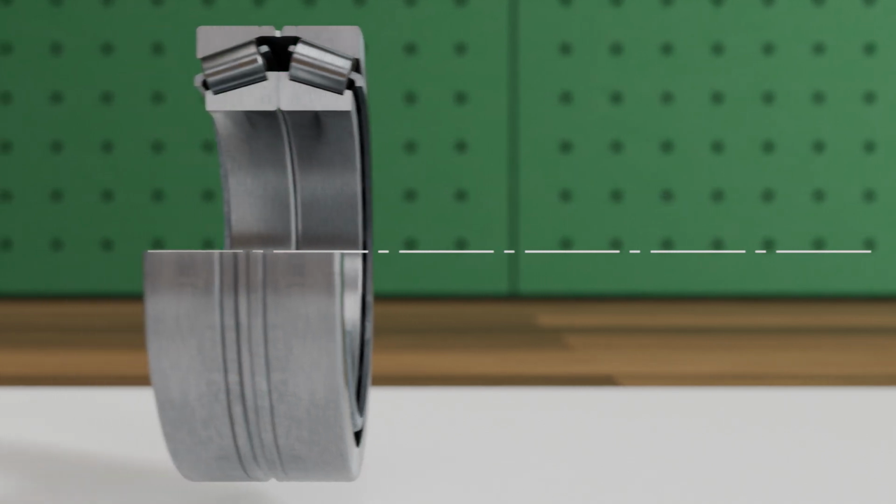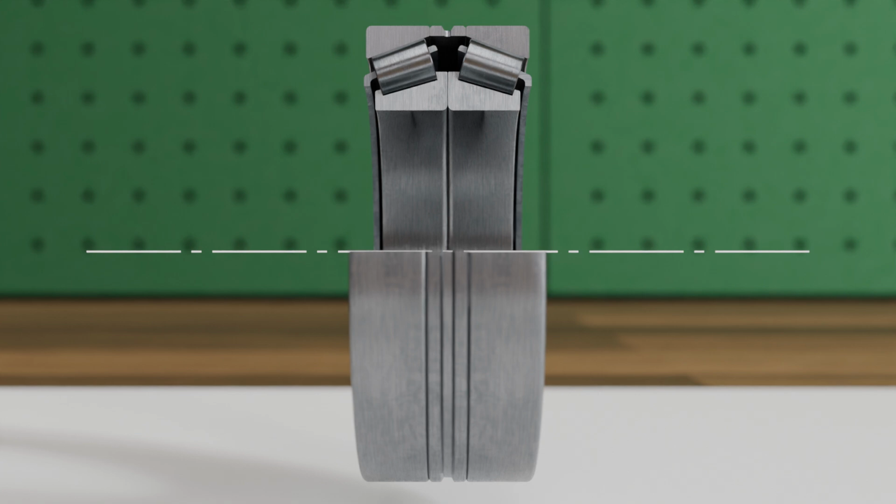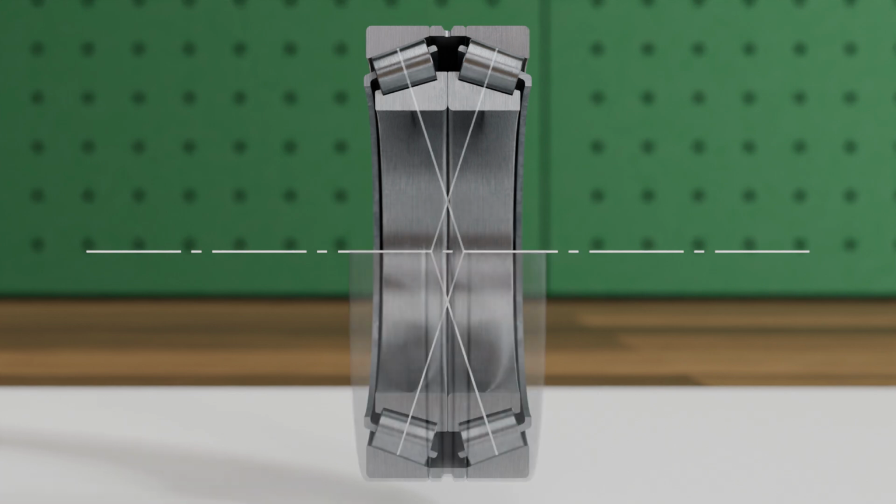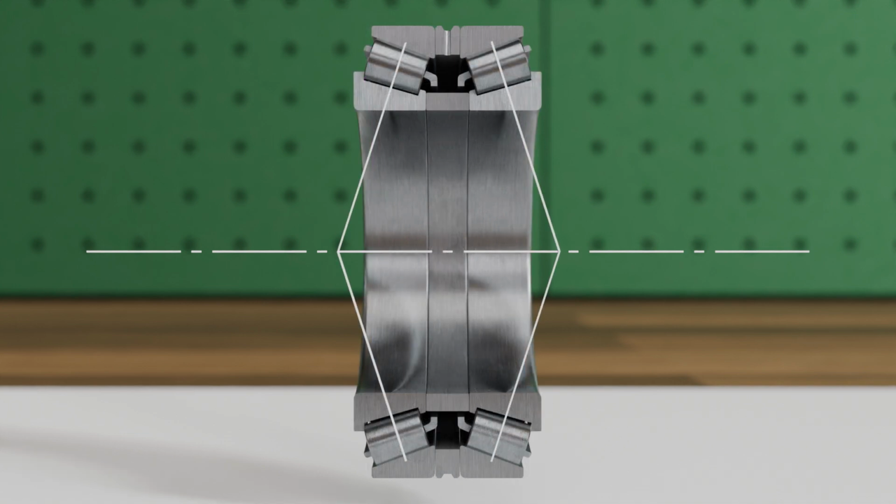Matched tapered roller bearings are factory-matched bearing pairs, used together as a set, similar to the face-to-face or back-to-back arrangement in angular contact ball bearings. In the face-to-face arrangement, the load lines run toward the bearing axis and intersect inside the bearing. This design allows for compensation of minor misalignments, and is especially suitable for shaft side expansions or slight shaft deflections. The back-to-back arrangement, on the other hand, has load lines running outward that intersect outside the bearing. This results in high stiffness and good resistance to tilting moments,